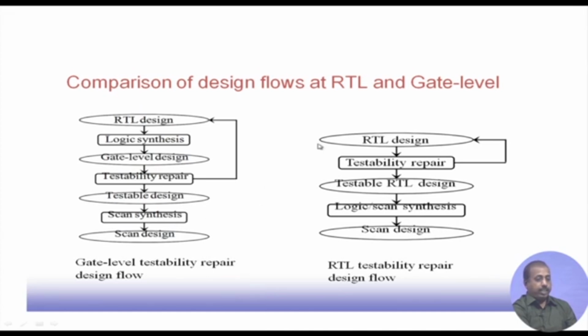On the other hand, at the RTL level, if we start at the RTL design, then we do a testability repair. So, we see whether there is any feedback loop, whether there is a gated clock and all that. All those tests are at the RTL level. So, we get the testable RTL design. After we have got this testable RTL design, we do the logic and scan synthesis, and that way we get the scan design. So, testability modules are inserted at the RTL level itself.